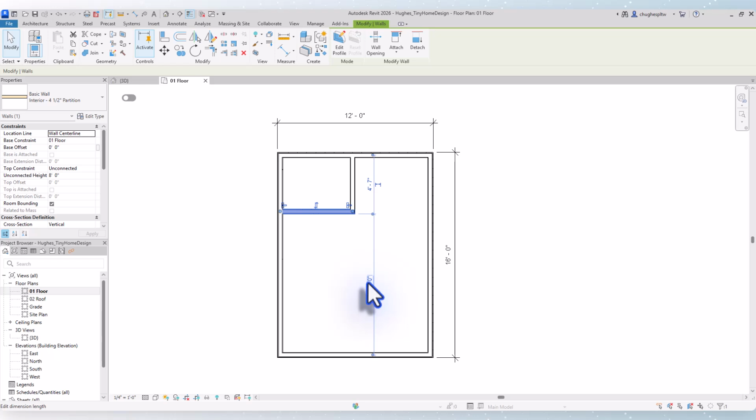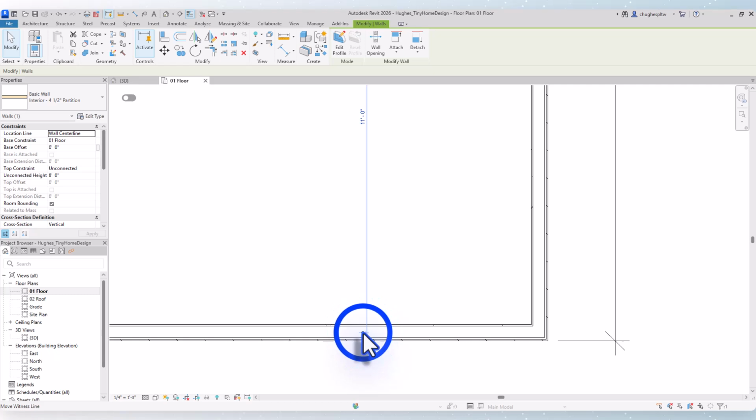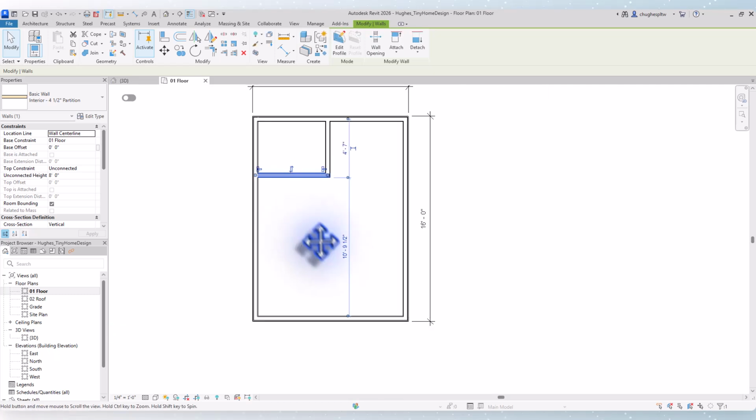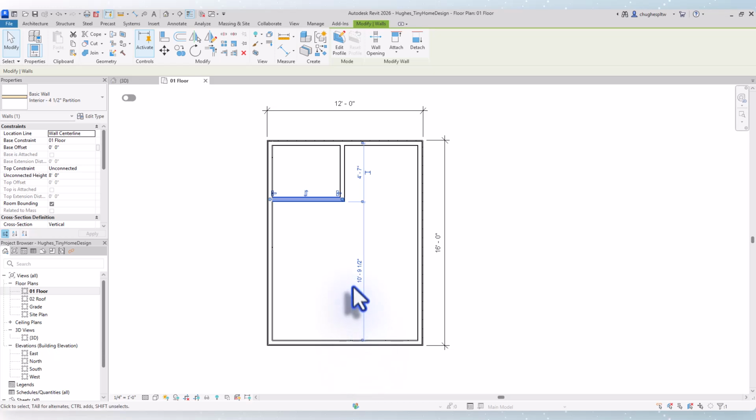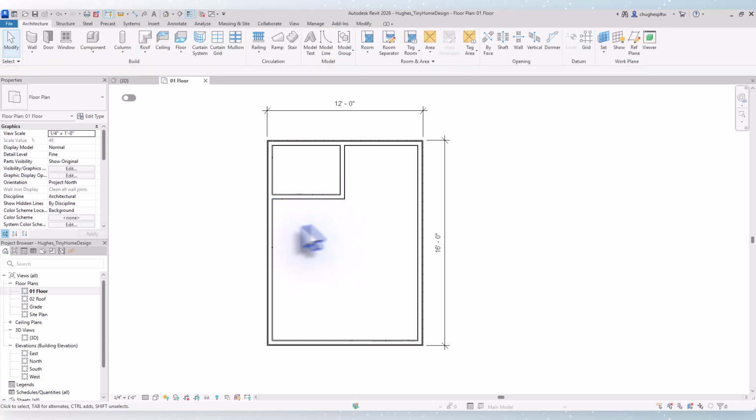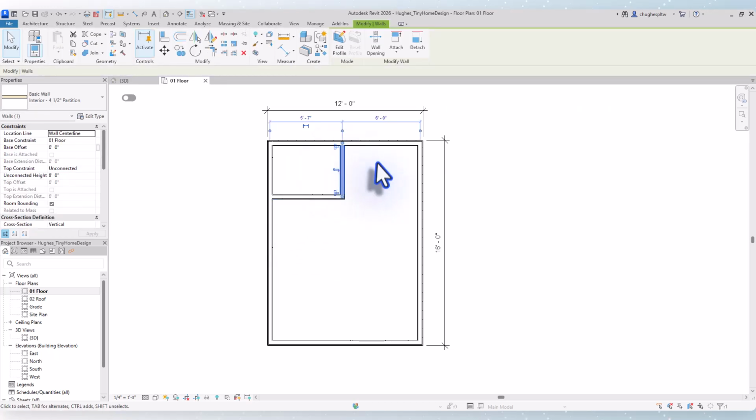And if you want it to be further away, then obviously, from where this is measuring to, you can do that. Again, watch where you're going to right now. This is to the center line. So this is going to the inside edge. So now you'll see that when I change that, that dimension is different. So you do have to watch those witness lines. So I'm going to go ahead and hit 11 and then set that in there. Don't have to do this. It's just an example. And so that's kind of what's going on here.